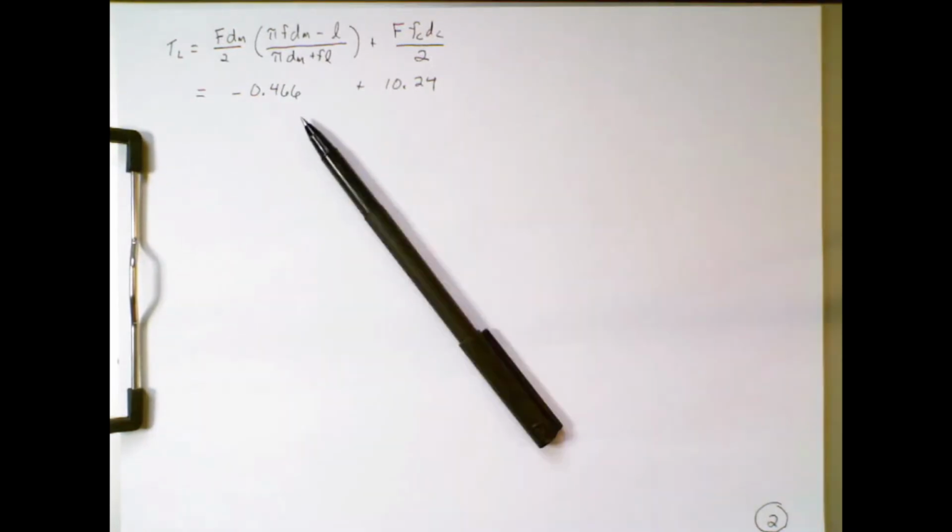Well, this first term, recall, is the friction contribution to torque as well as the torque required to raise the load. And it's less than 0. So remember, if the lowering torque is negative, that means that our power screw is not self-locking, at least by itself, just looking at the screw itself. But there's more to the screw than just the interface between the threads and the nut.